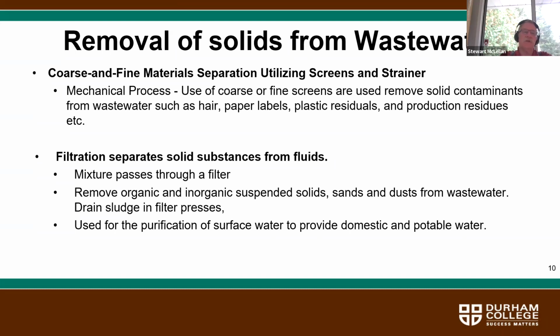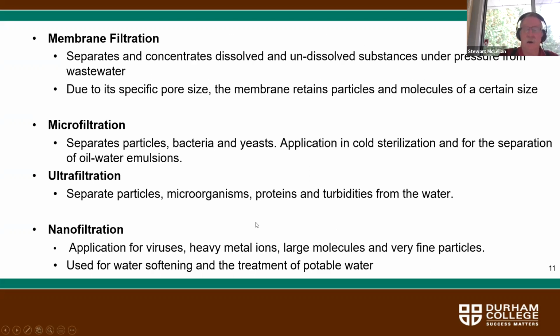It is something that is actually monitored in industrial wastewater discharges. Your biological oxygen demand needs to be below a set limit. I believe in most municipalities it's around 150 milligrams per liter. But essentially the BOD is somewhat of a surrogate measure for the amount of organic materials in your water that can be easily broken down by bacteria.